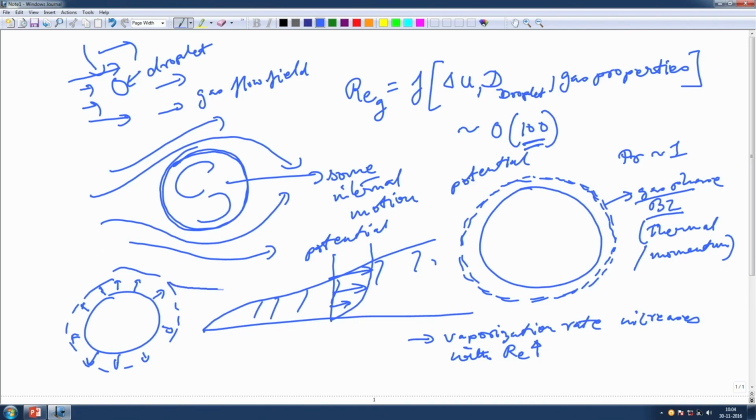After that there is a diffusion gradient which slowly takes away this vapor, that is the diffusion flux to the far field, and that is how it relieves the vapor concentration here, so that more liquid can escape. Now, if you have a convective flow, it will blow away this vapor much more conveniently. As a result, your vaporization rate should actually increase.